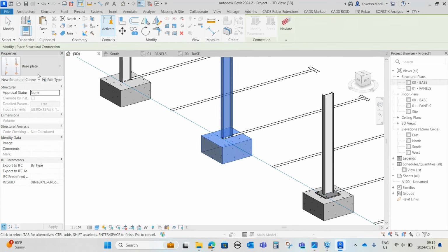So I'm just gonna open up the east elevation, change this to fine. So we're gonna place our beam that's gonna be set diagonally. So I'm gonna press VG just to see our base plate, and then go to structural connections and then check this, apply, and then okay. Now I can see my base plate. So from there, I'm gonna load in my beam insert, and then go to load family and say metric library,